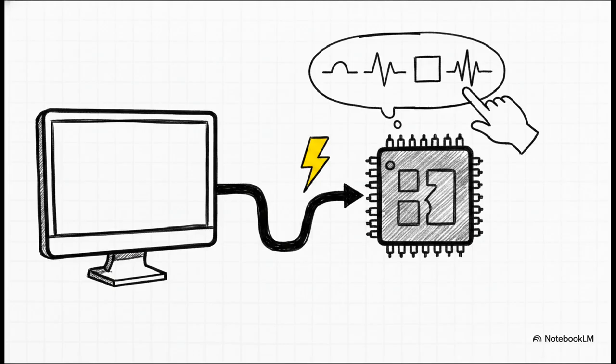Because the differences between those 4 waveforms exist entirely in how the instruction memory is arranged, the engineer could swap between them live. By just editing numbers directly in the in-system memory and pushing them over JTAG, they changed the physical behavior of the chip in seconds. There was no recompile, no resynthesis required, just instant, qualitatively different behaviors observed right there in physical silicon.